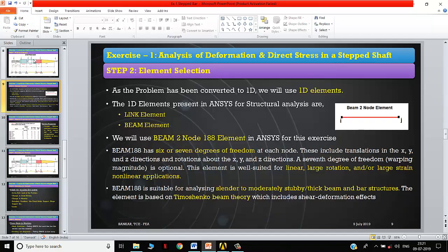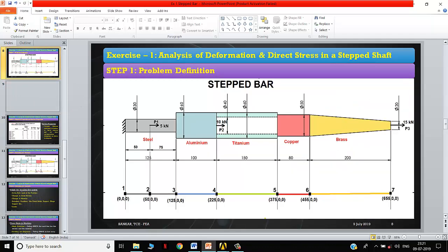In order to solve this problem, while solving using any FEA software, not only ANSYS, which I'm going to teach you, first of all, try to simplify the problem. As you know, every problem in nature is three-dimensional, but you don't need to solve it the way it is. You can simplify the problem to a two-dimensional problem or even a one-dimensional problem. As you simplify the problem, the solutions that you get will meet your analytical solution very closely. The error is reduced very much.